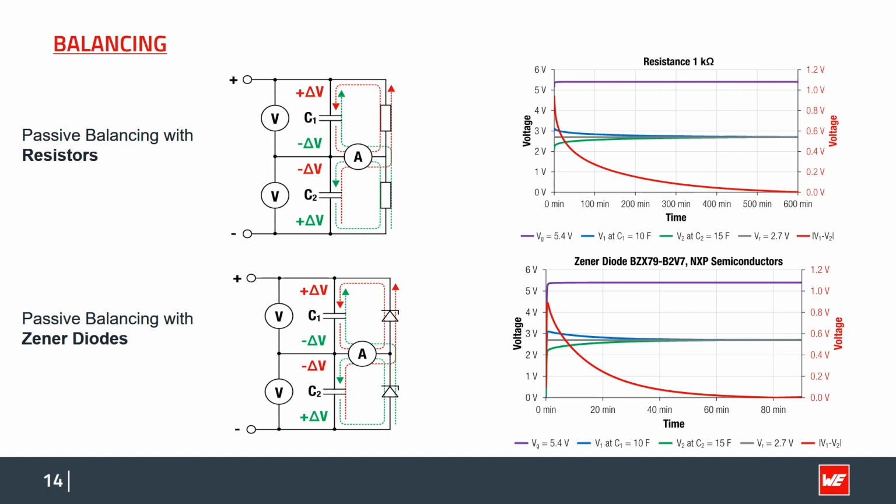In a series connection of supercapacitors, you may have the situation that you have connected two capacitors with two different capacitances. If you then apply voltage, the voltage drop over each capacitor is not equal. The capacitor with a lower capacitance will see a larger voltage than the one with a higher capacitance. Thus, you may risk overvoltage. To prevent that, you should employ a balancing.